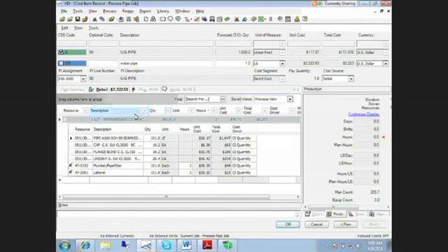Okay, but you can see what it brought in now. There's the assembly that it brought in, that intermediate carbon steel pipe spec assembly. The 101.8 feet came in from OnCenter, from our takeoff, and now it brought in all of those things underneath for all of the values, right? So we've got our pipe, our caps, our flanges, and that kind of stuff. We didn't set up our assembly very well for our man hours there.